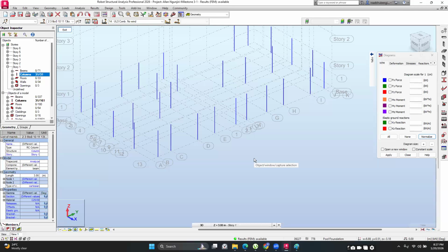Okay, so what you do is you always try to group them. You get to see which columns have loads that are within the same range. You get to decide on a range. For the interior columns, I want to group, say, any column with a load higher than 1500 kilonewtons, and design them with this particular load.